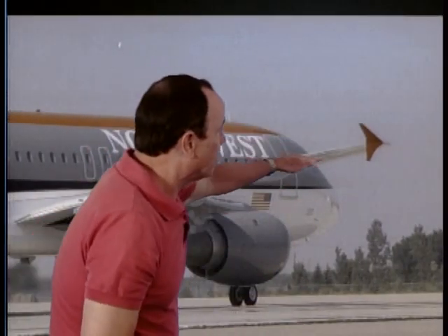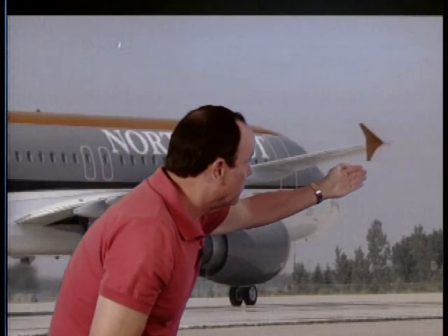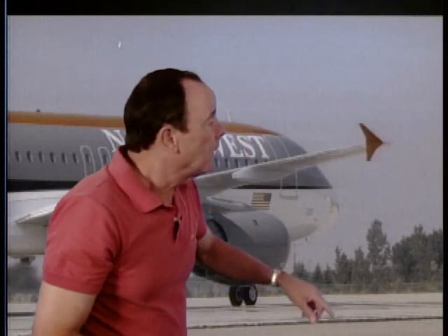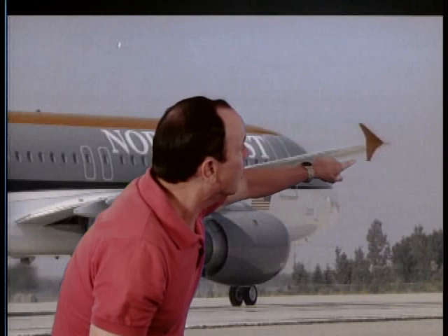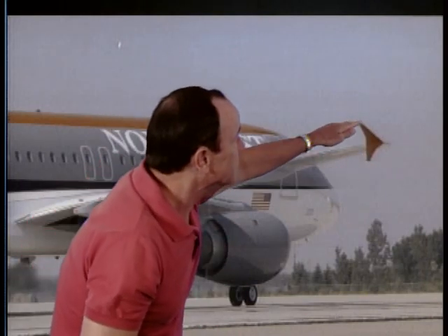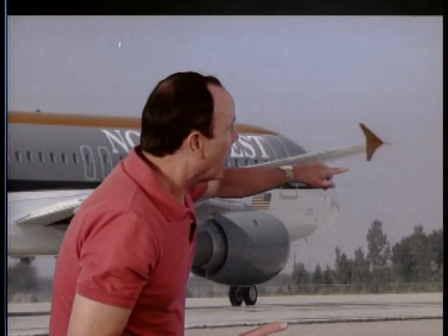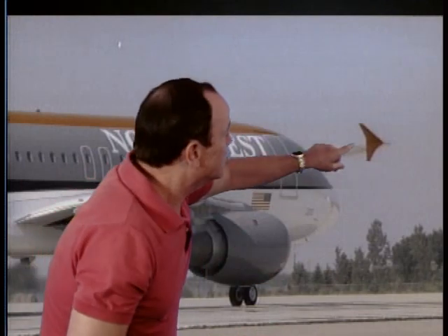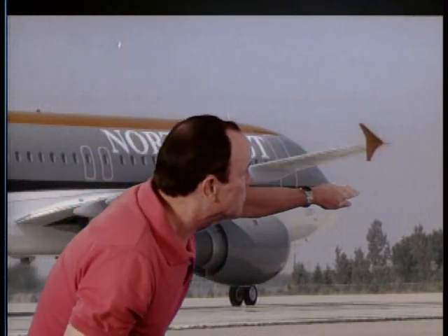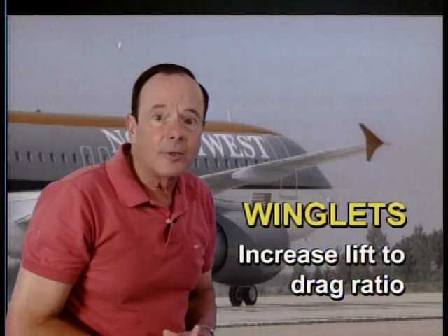And here it is on an Airbus, on a Boeing 747, it goes up. On an Airbus, it goes both down and up. But what it does is interfere with the flow of the air around the wingtip, and it minimizes these wingtip vortices, and therefore you do not have the loss of lift and increased drag that you would have had. So the desired effect from these winglets is to increase lift and reduce drag, and so they increase the lift-drag